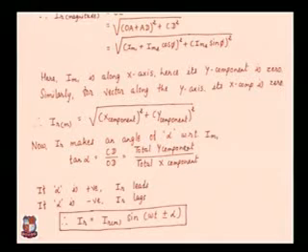If you have a number of currents, suppose 3 currents, then the total y component of all the 3 currents divided by the total x component of all the 3 currents gives you the value of tan alpha, and tan inverse of this gives you the angle, which is the phase angle of the resultant value. If alpha is positive, it indicates that your resultant current is leading, and if alpha is negative, then it indicates your resultant current is lagging. So your final equation for the resultant current is written like this: IR is equal to IR magnitude sin(omega t plus or minus alpha). The value of alpha depends upon the x component and y component of the current. It may be leading, it may be lagging, depending upon the magnitude of currents or behavior of the circuit element.